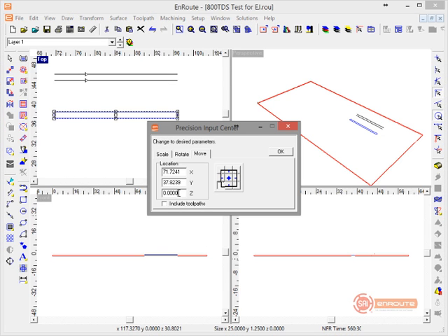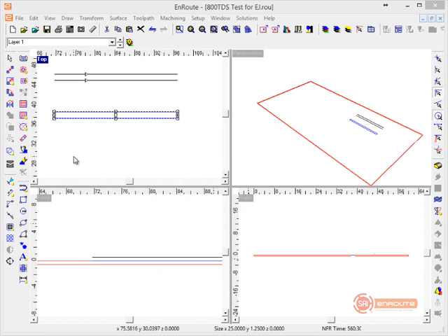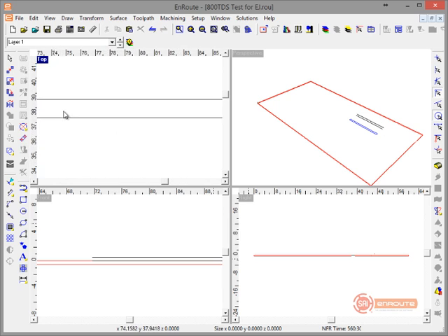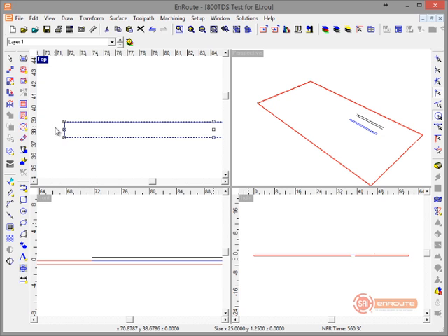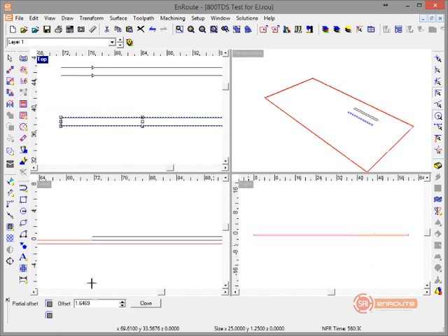All right, so we're moving that back to 0 just because I like to have that rectangle at 0. So there we go. Now I'm going to create a mask here. The problem is, when I'm toolpathing this, I don't want to go past the side, but I probably do want to go past the top and the bottom a little bit. So just so I can make sure that the tool goes all the way to the desired area, I'm going to come here and do offset partial contour.